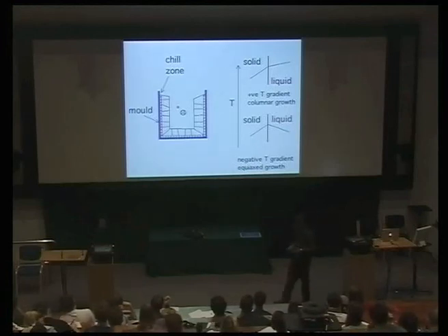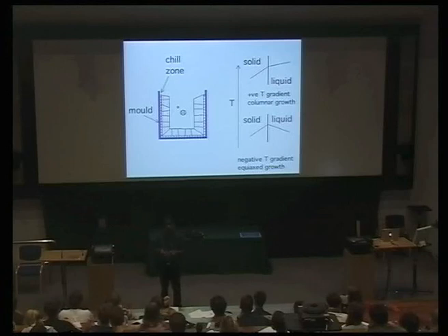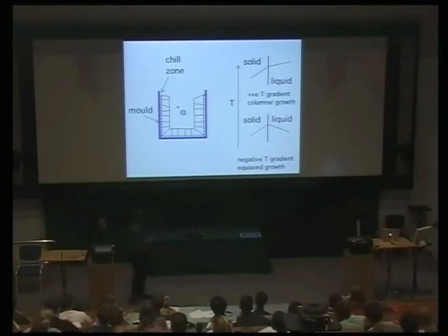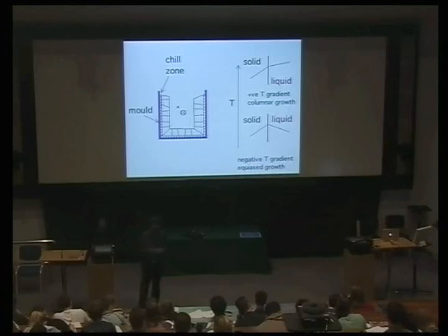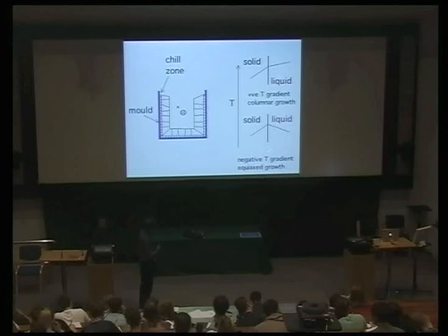That's the normal scenario. But it's possible that you generate a lot of heat at the solid-liquid interface, because that's the enthalpy of fusion. Okay? Now, if you're generating a lot of heat at the solid-liquid interface, then the temperature here might actually be higher than the temperature further away in the liquid. Okay? In that case, this liquid here, you will get some nucleation on dirt particles. Okay? Now, this is a scenario which actually makes this interface unstable.